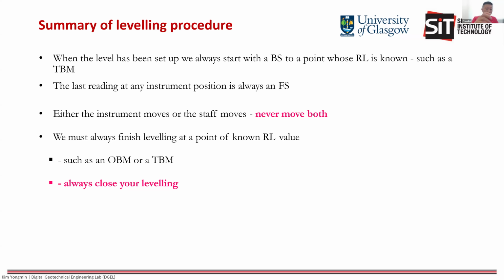If you still remember how to read the staff, as I mentioned, there are always some different interpretations, whether it's 2 mm or 3 mm. So that can contribute some errors, and also the instruments may contribute some errors. So when you transfer a few points, the error may become bigger and bigger. That's why you always need to check back with another benchmark to counter-check whether your readings are correct or not. Is that accurate or not?